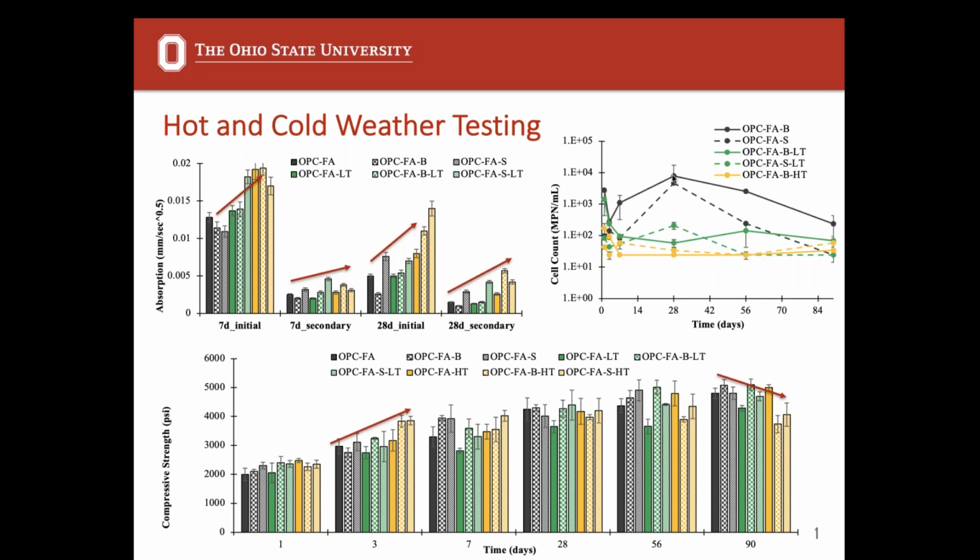in order to get good biomineralization. You also need to know what the dosage amount is to put into the concrete. All the literature before that we looked at was really unclear about how they were adding bacteria and in what proportion to the concrete. They said they added 10 to the 8th bacteria. So I think they took a solution with 10 to the 8th vegetative cells, and they didn't pay attention at all to the spore count, which is really what matters. So we need to know more about how much we need to put in, how much need to survive in order to actually cause the crack healing.